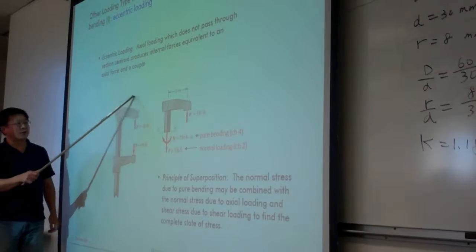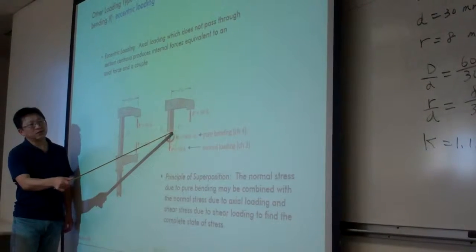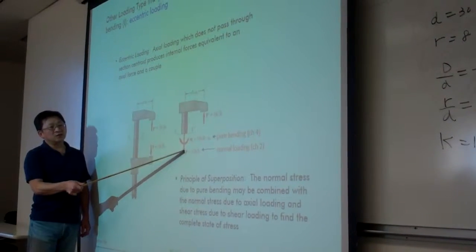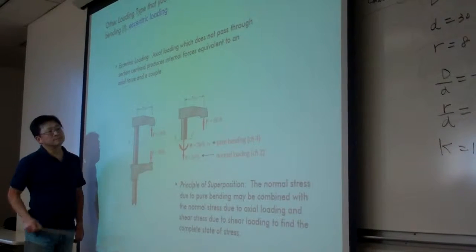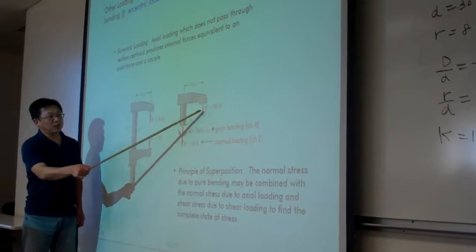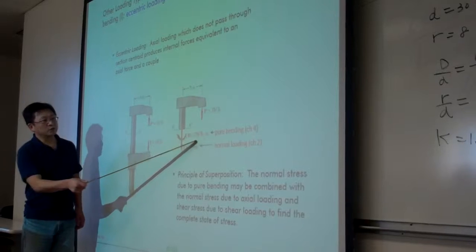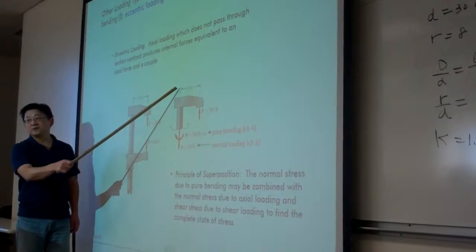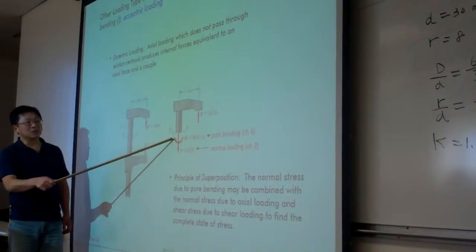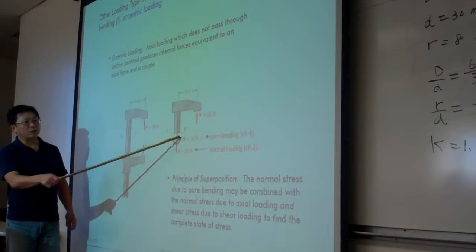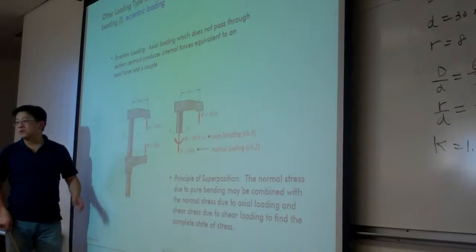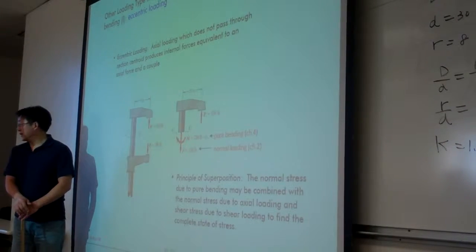If we take a free body diagram on the upper portion to expose this cross section here, you can tell by force equilibrium in the y direction, this is a reaction force in magnitude equal to 150. Also, in taking the moment equilibrium, you can see this pair of forces will produce a net counterclockwise rotation. This moment must be balanced by a reaction bending inside this section. So that is the counterbalanced reaction, and the magnitude will be equal to the force multiplied with the arm, 750. This is traditional statics. Should be very easy, straightforward.